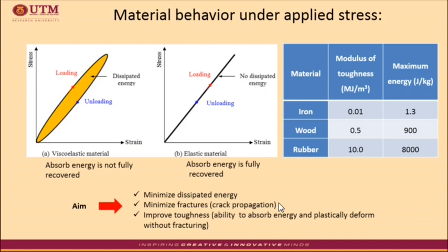The elastic contacts obviously provide a higher ability for the specimen with rubber particles to absorb energy under the imposed stress before rupture. This is termed material toughness, which is associated with the increments in strain. The material toughness can be calculated by measuring the area under the stress-strain curve.